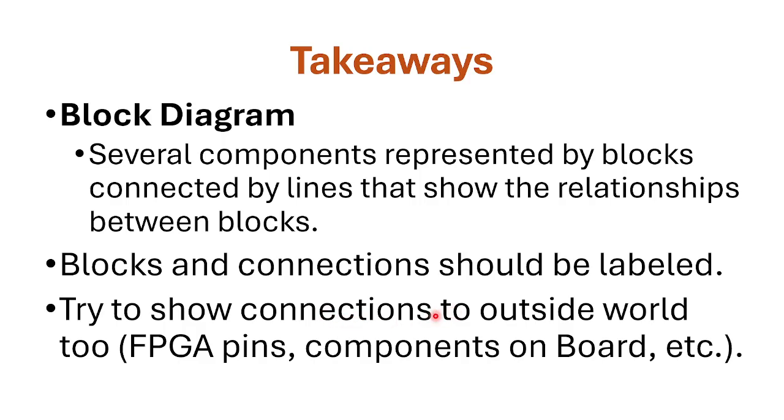And you should also show connections to the outside world, going outside the FPGA and coming in, connections to different things on the board or other breakout boards that you may be using in your design. So try to provide as much information on the block diagram as possible, while not complicating it and making it too messy either. So that's pretty much it.